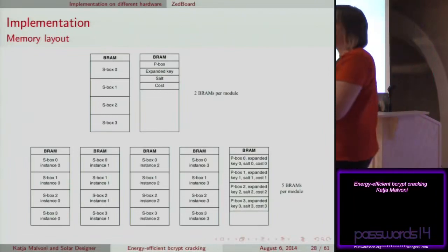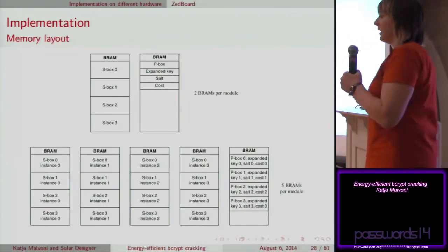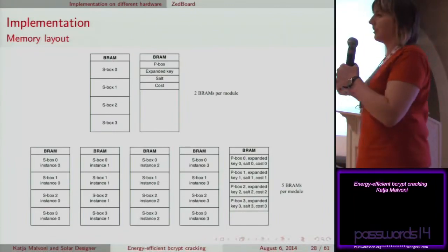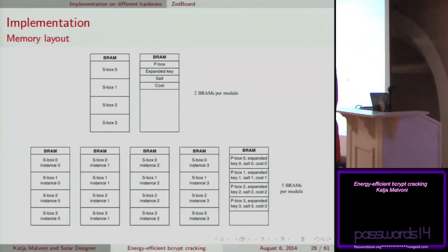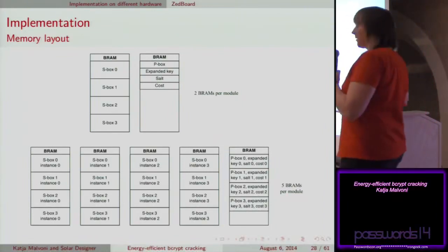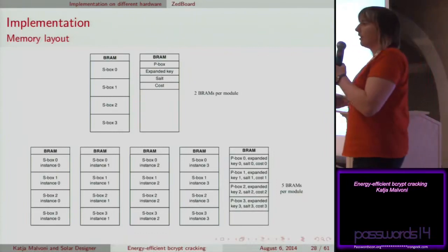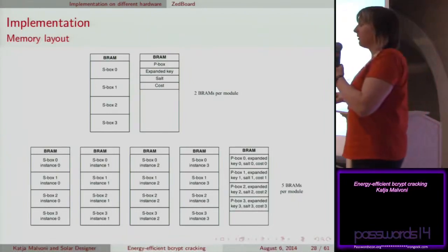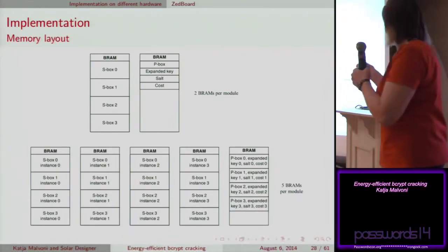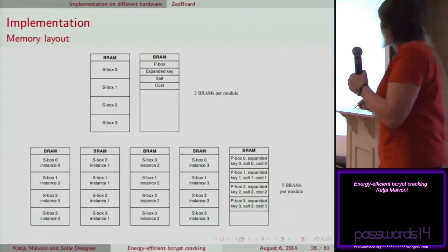Well, the reason we don't do it is because each of those VRAMs has 2 ports for read and write. So in one clock cycle, I can read only 2 values out of this VRAM. And as we saw earlier in bcrypt, I need pbox values on every round of Blowfish encryption, so I need them in every second cycle. That's the reason why this isn't filled until it's full.